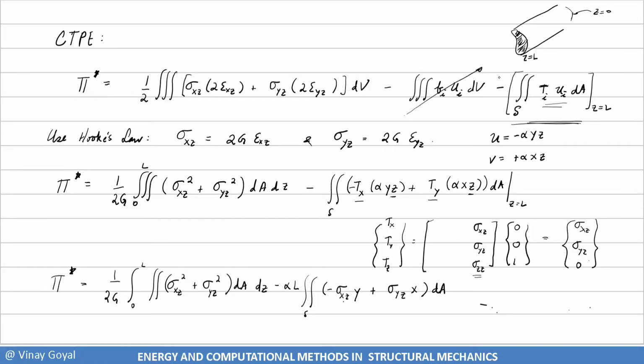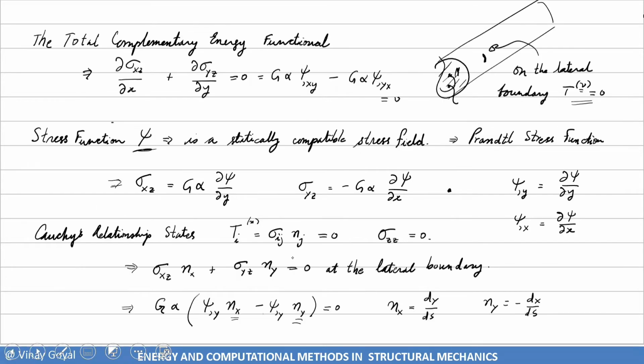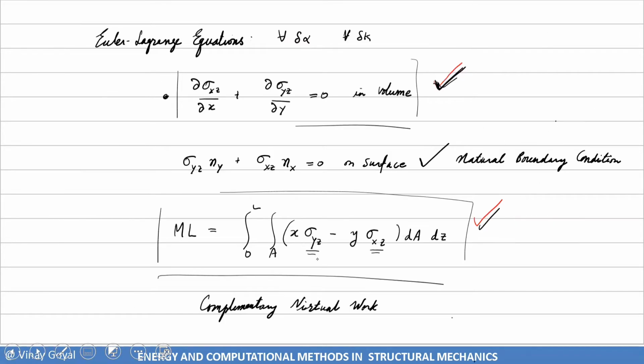So what are we trying to accomplish? Let's try to remember. So I used the principle of virtual work and I came up with these equations, but these equations are not very useful. I mean, they are useful, but they're not letting me figure out how to come up with torsional constants for the various cross sections. If I apply a moment, I can't really figure out what the warping is, and I may not be able to calculate the rate of twist based on these equations.